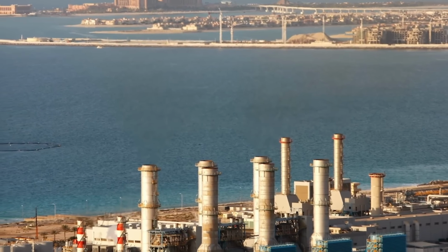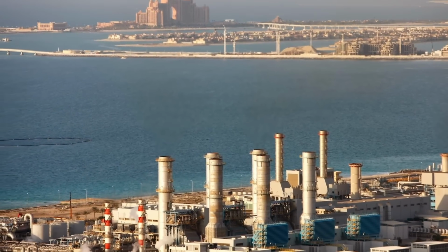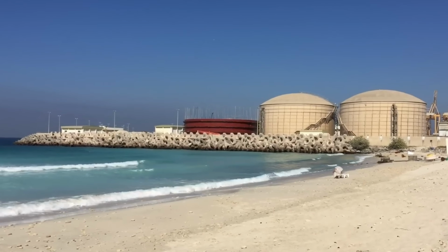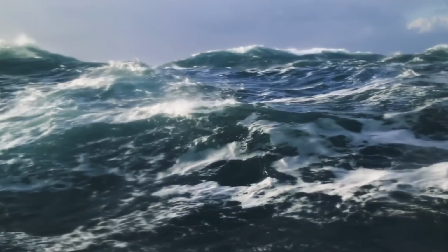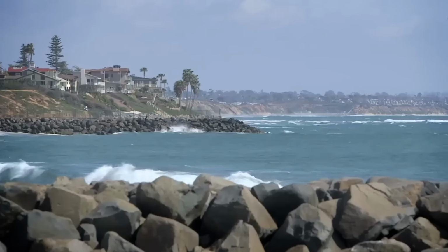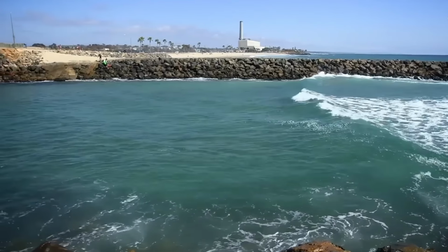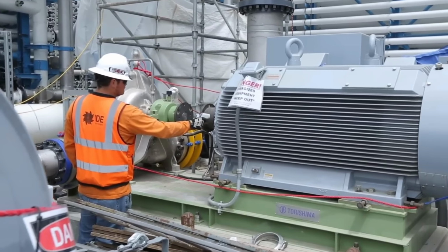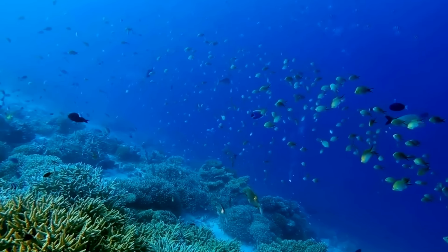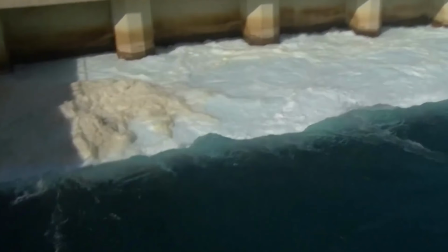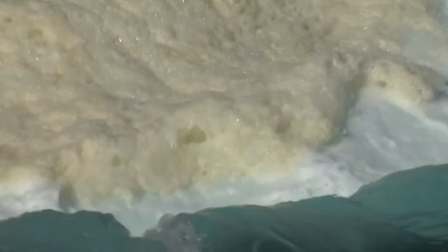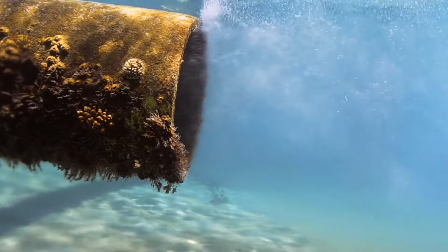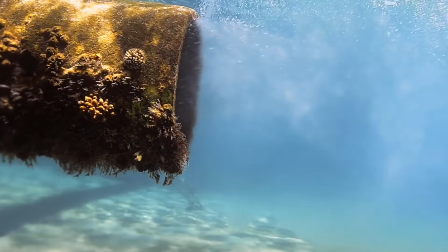California water authorities, for example, identify multi-port diffusers as a preferred method for dispersing dense brine discharges from new facilities where raw brine is released to the ocean. The design depends heavily on the location. Engineers have to consider water depth, currents, waves, seabed conditions, and the volume of brine being discharged. The goal is to bring salinity back toward the surrounding ocean level within a defined mixing zone rather than allowing concentrated water to collect near the bottom.